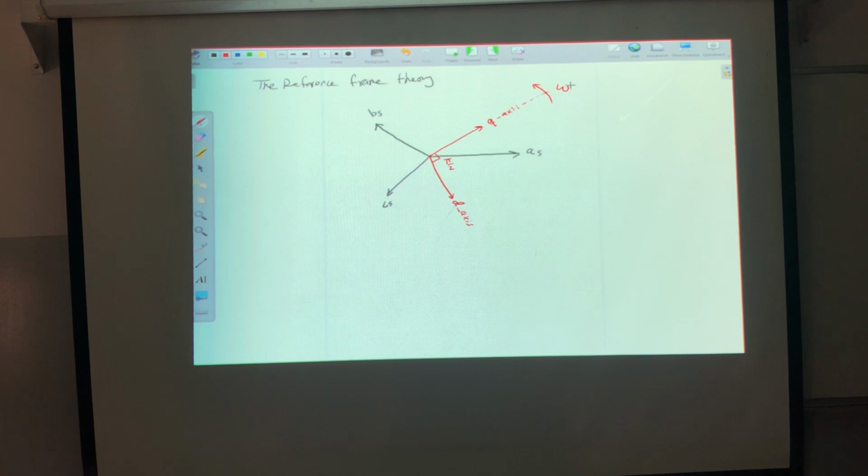If omega equals omega r, it will be the rotor rotating reference frame. If omega equals omega s, it will be the synchronous rotating reference frame. So instead of discussing three frames, I can discuss one, the arbitrary reference frame. Then after that, I can specify which speed I need the frame to rotate with.